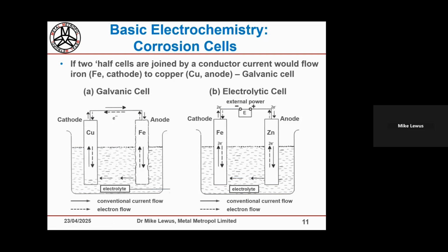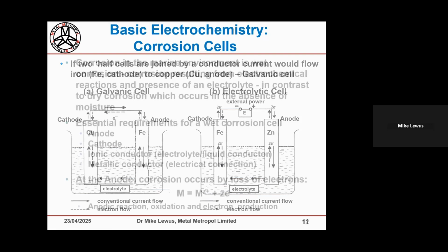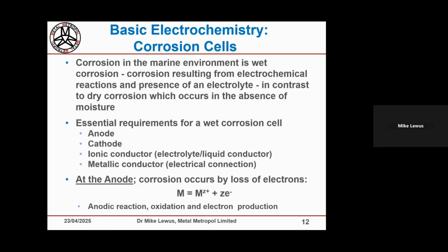And some of you, if not all of you, will be familiar with the fact that anodes in ICCP systems can be anything, and they're usually very noble metals because we don't have to particularly look at finding a very active metal like aluminium, magnesium, or zinc, as we do when we conventionally want to protect parts on a leisure vessel, whether it's a motorboat or a sailing yacht.